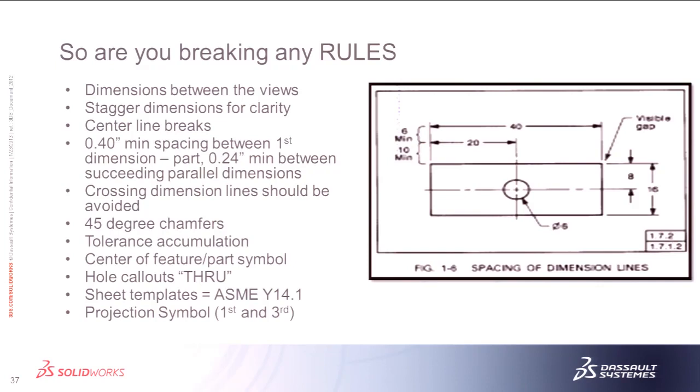And one thing we do to prevent that a lot of times is, we'll dimension a pattern of features on one side of the part, and sometimes maybe the overall dimensions on the other side of the part to keep from crossing those dimension lines.